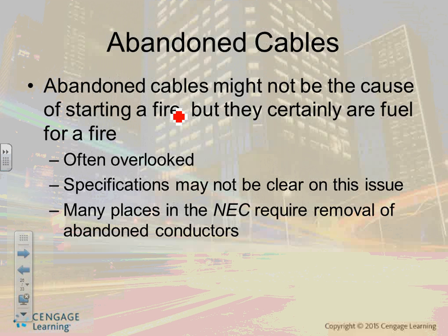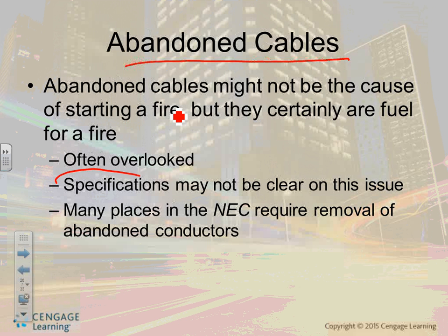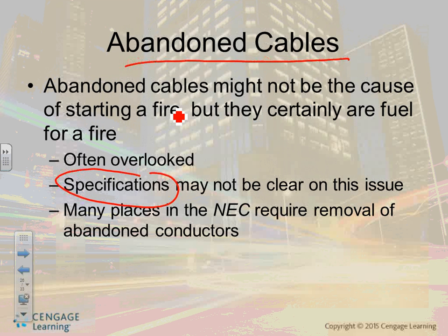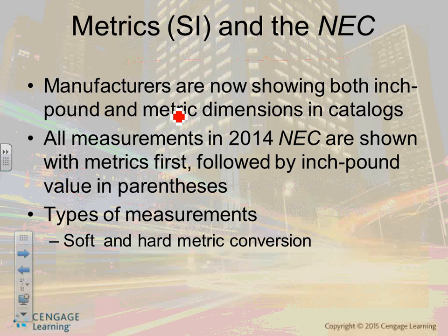Okay, moving on, away from the engineering. Abandoned cables. The code book requires you to remove them, though some specifications are not clear about it. If you have abandoned cables, especially fire alarm, security, phone and data, what do you need to do with abandoned cable? Remove them. So you put it in your specification that the electrical contractor must remove all abandoned cables. Why? Because if there's a fire, they don't initiate the fire, but they will contribute to the spread of the fire. You'll see these all the time.